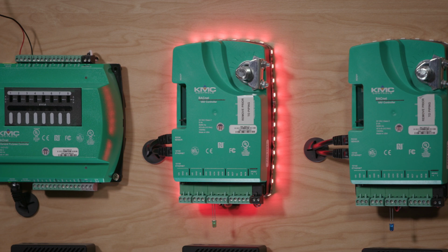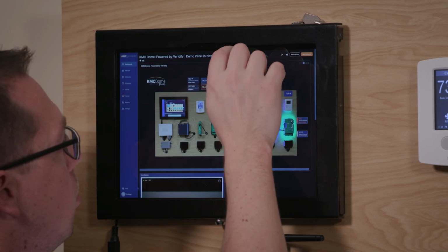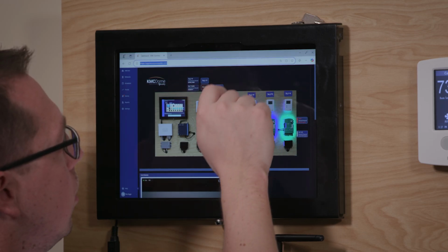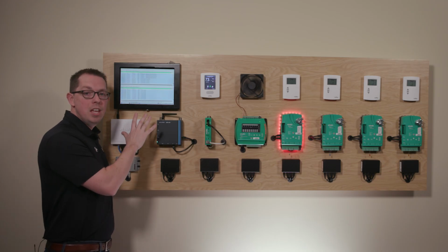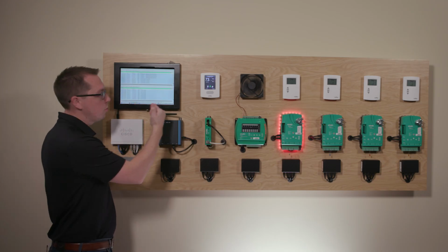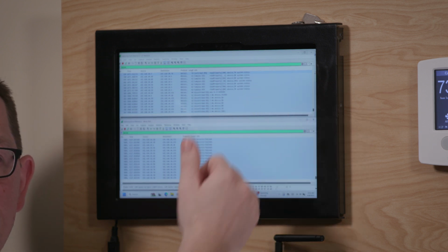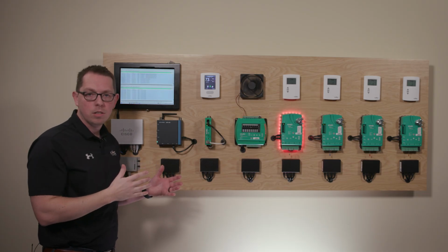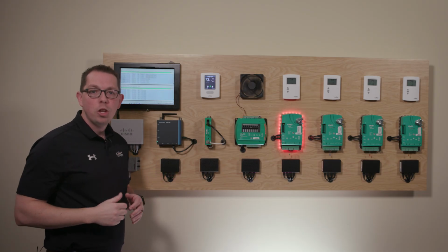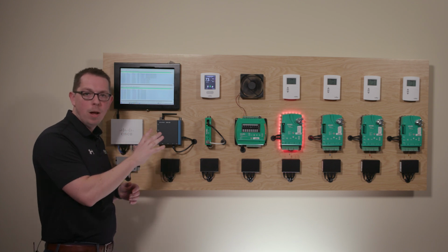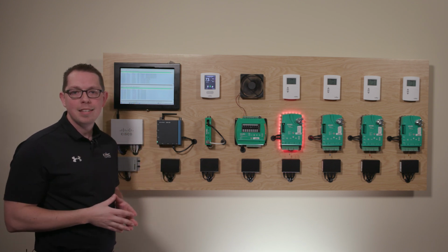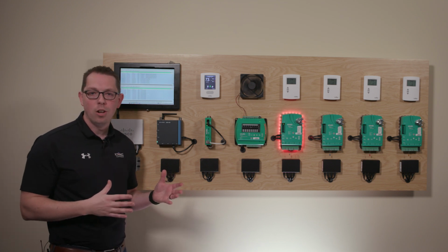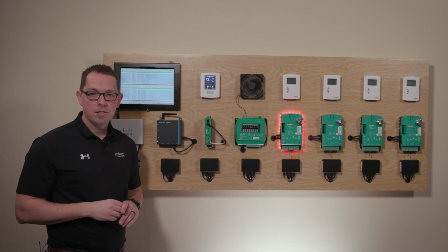All right, so I've turned this red light on. Let's go back to our Wireshark. As you can see on the open BACnet side, all the messages are readable in plain text. Anyone that has access to the network, even a malicious insider, could intercept, modify, or disrupt these system commands. This is how attackers can manipulate HVAC systems, disable security alarms, or even shut down entire systems.